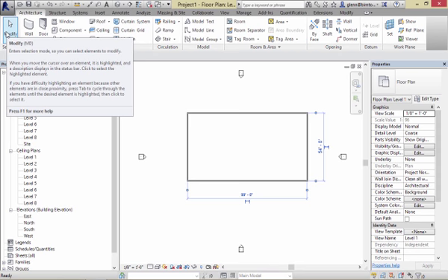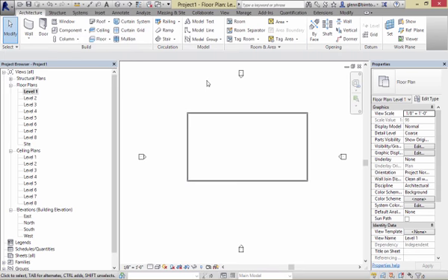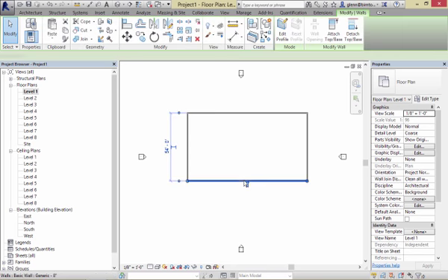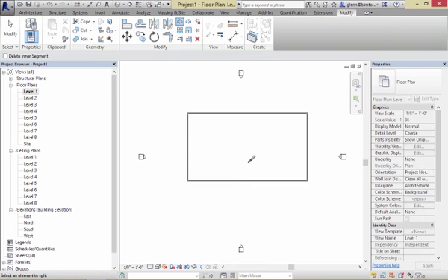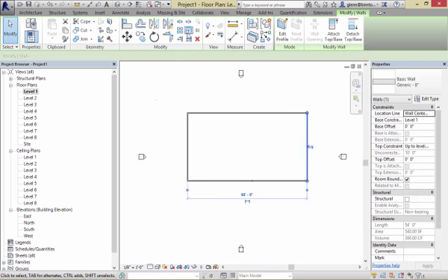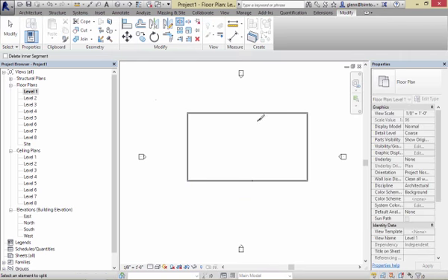What I'll do is go through and choose that wall. I'm going to split it. I'm going to split the corner right here. I'm also going to split this one. So I'm just using a little split tool. Again, what I did was just choose the wall. The modify tools come up, and split is one of the choices there.